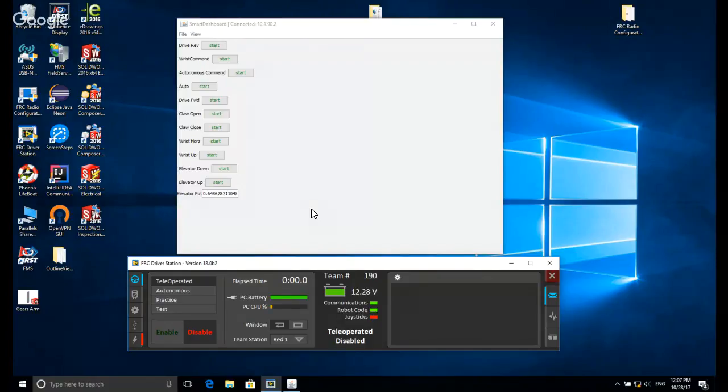There's a little space right here, right? What the I value does is it says, I'm going to add this up, and then add that to the motor value. And then I'm going to add this and add it to the motor value. So what ends up happening is this will start to go up and then eventually end at the set point. So the I value gets rid of this error here, which is called the steady state error.